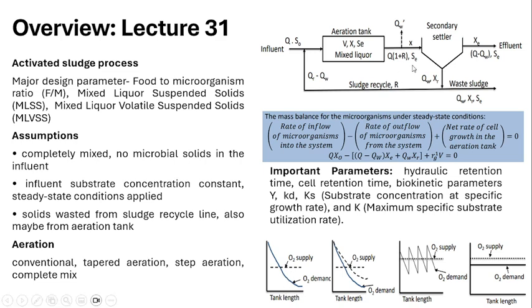So coming to week 7, this week is about the secondary treatment equipments, mainly the process equipments used in the secondary treatment. I have already explained what the secondary treatment is. In the primary treatment, by gravity settling and sedimentation, the larger solid particles are removed from the wastewater. The organic matter content is decomposed into carbon dioxide and water using microorganisms in the secondary treatment. Many equipments like the activated sludge process, trickling filter, and lagoons are used in the secondary treatment of wastewater.